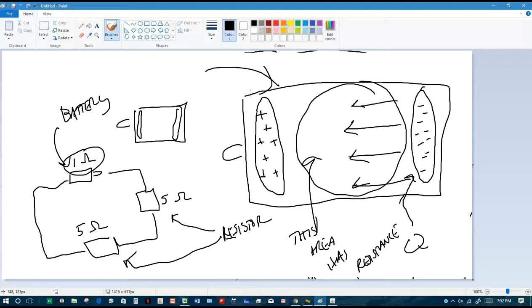No. What would it be? It would be 5 plus 5 plus 1. Exactly. That's the battery. It would be 5 plus 5 plus 1, like you told me, because the battery itself has some resistance of 1 ohm. So the total resistance of the whole entire circuit is really 11 ohms, because the battery itself adds some resistance to the circuit.